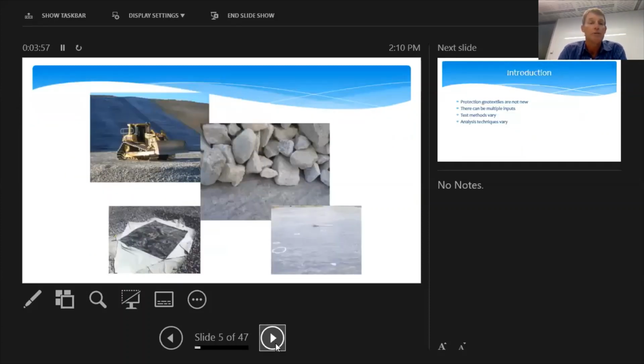So in general, what we're talking about in liner systems is an HDPE base liner, which is overlain by a geotextile that provides protection from the drainage gravel which is laid across the top of it. And what you can see in these slides is a typical example of a relatively large dozer spreading drainage gravel across the geomembrane protected by a thick non-woven geotextile. And when it works properly, it works really well, but then you see the bottom two slides, and that's when it hasn't worked terribly well, and there's holes punctured in the liner. And that's really what we want to avoid.